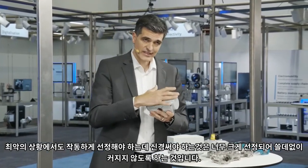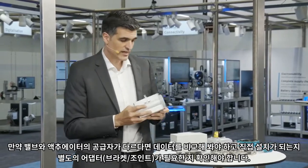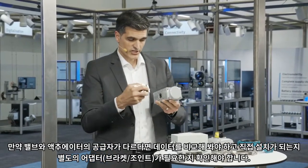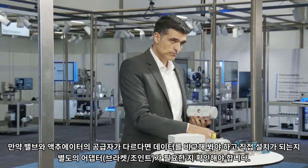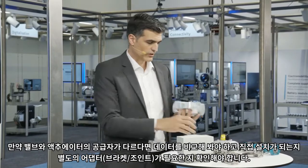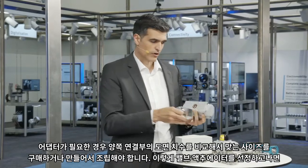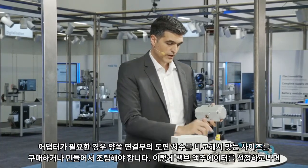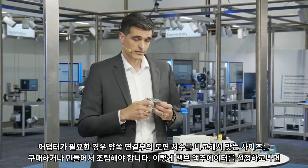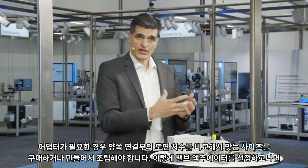Once you know what is the size of the actuator after having to search in different data sheets from different suppliers maybe, does it fit directly to your process valve? Or do you need to find some adapters that you have to install between the actuator and the process valve in order to adapt the interface of both products? If this is the case that you need such adapters, then look for those adapters in the different catalogs and order them.